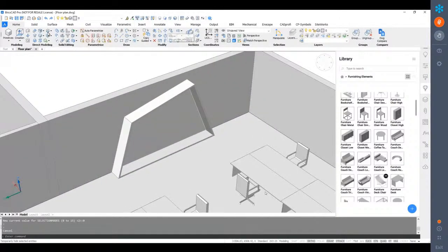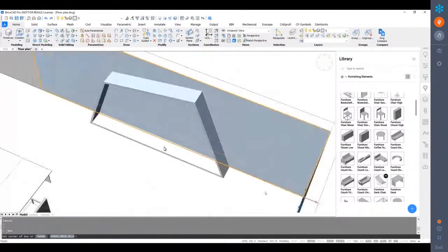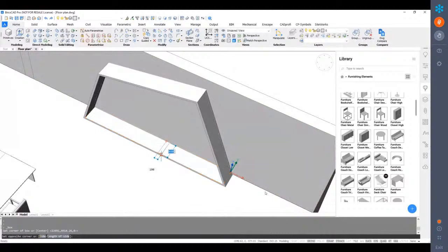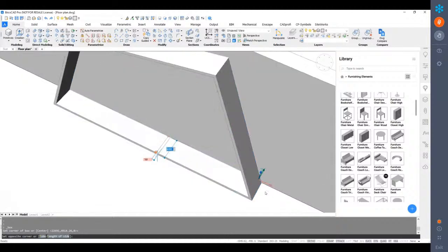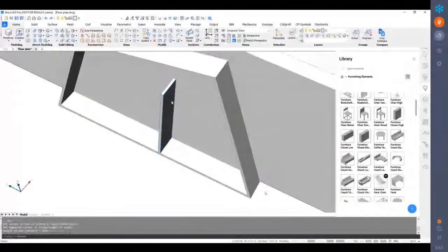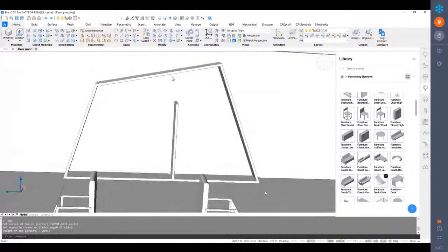So now the next thing for us to do is create the shelving actually inside our design shelf. So I'll just use a usual box tool. So the important thing for me right now is the thickness of this. I'll just put it at 50 and make sure I am putting it at 450 because that's the thickness of the shelf that we did earlier. So, okay, and then I can immediately bring it up. So I'll just bring it up halfway for now.